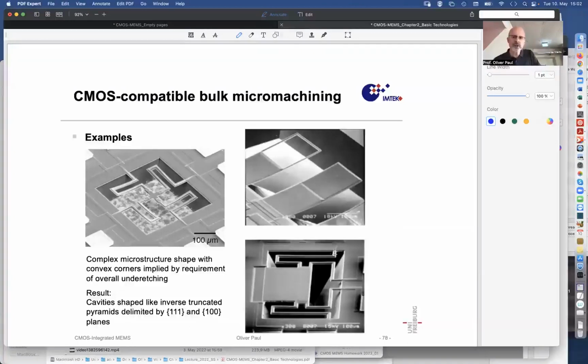They're usually oxidic layers with a metal layer running along to feed here, for instance, a resistor, or here to feed another resistor via these two arms to heat up that structure, for instance, at this location, and then at this location to measure its temperature increase, and here at this location to measure the temperature of the chip, to know what the gradient is. And one already has a test structure for measuring the heat flow across thin materials, which means that you have a test structure for determining the material's thermal conductivity.